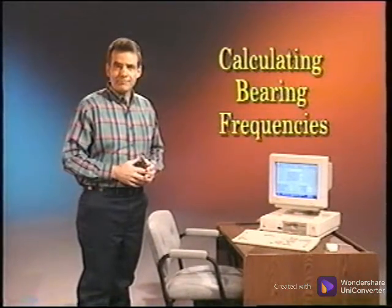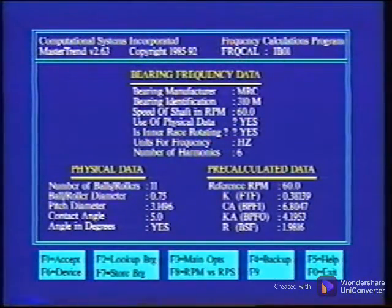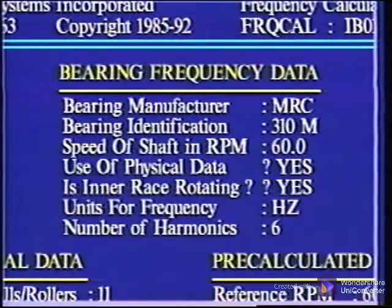This screen is the bearing calculation screen for inputting data about the bearing. A report is then generated showing the calculated frequencies for each component of the bearing. After entering the bearing name and number, 3 other fields are important. The first is the Use Physical Data field. Toggling this to Yes enables us to input the actual physical dimensions of the bearing.